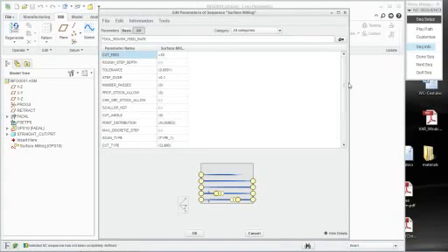The site file allows you to take off parameters that you're not going to use and also standardize those parameters. So if you have a machine where your coolant is always on, by default in the machining software it's always off. So that's something that you would have to change every single time. So in this case, what you can go into is your site file, make that standard in your site file, apply it, and then that coolant would always be on, and then you don't have to deal with it. Okay, so a really good way to standardize the parameter fill out as far as speed, feed, and depth of cut.